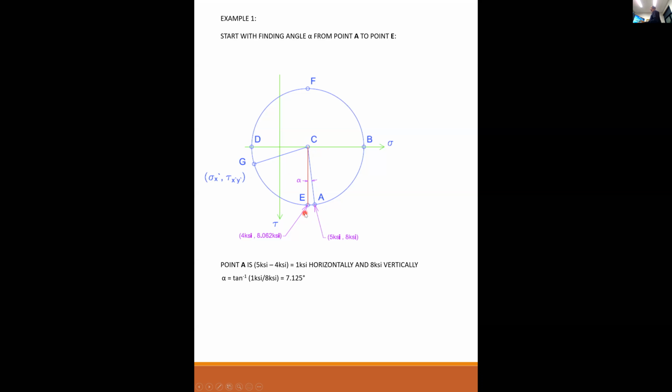So the inverse tangent of 1 over 8 is 7.125 degrees. If I measure this in CAD, that is 7.125 degrees. So on the circle, it is 7.125 degrees. Now, what you're asking, and the question just before you, theta on this would only be 3.5 degrees. So theta would be 3.5 degrees, but on the circle, it is 7 degrees.